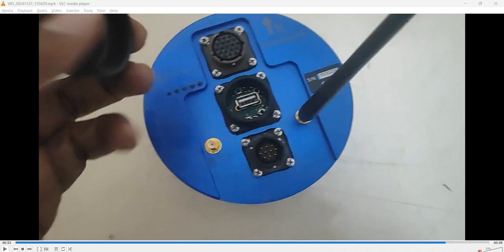The recorder must also take care of a few things other than recording the signal. It should also take the signal from the GPS and maintain the time, so that the exact time of the event will be known. So the availability of the GPS signal is also very important. When there is no signal from the GPS, you may be getting the data, but you are not able to get the exact timing.